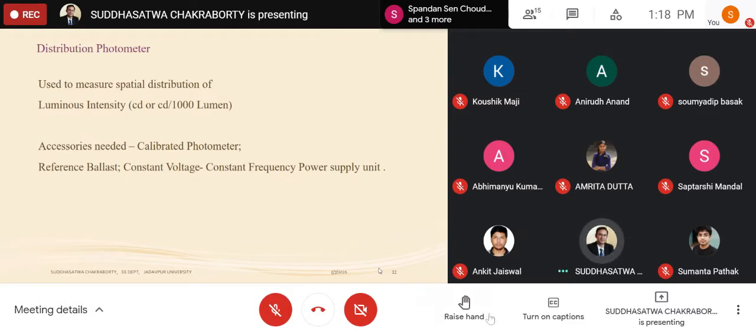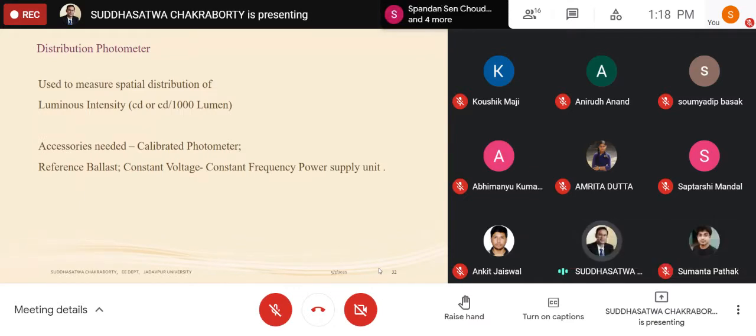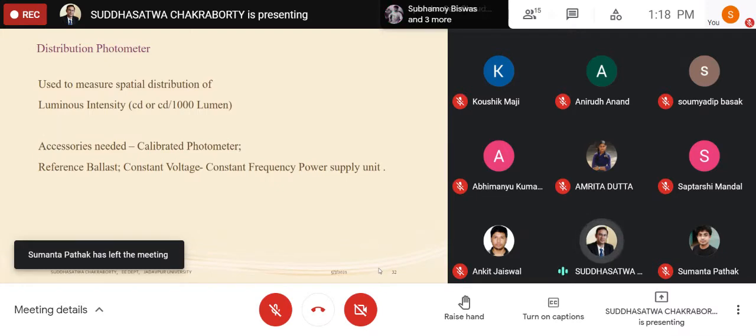So this methodology looks for measurement of luminous intensity at different angles. Already we have talked about the spherical polar coordinate system. We have already talked about the generic C gamma, B beta, A alpha type coordinate systems. We know that for indoor cases, we go by C gamma. For street lighting luminaire applications, we also go by C gamma. For flood lighting cases, we refer to the B beta coordinate system. So those types of coordinate systems are very much used. In our luminaire photometric classes, we have already seen how those coordinate systems become relevant.